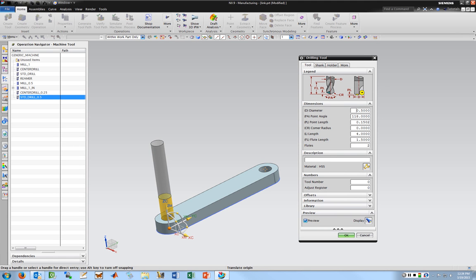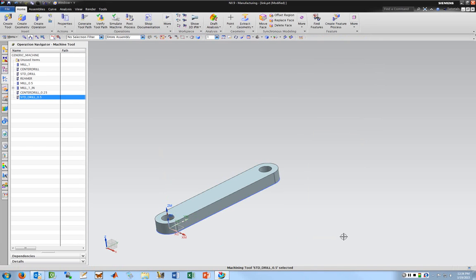At least I haven't had experience trying to do that before. But what I want to do is change the diameter to something under a 1/2 inch. So let's leave 10 to 15 thousandths. I'd have to look at a drill chart and see what the next smallest size is, but I'm just going to call it 485. There's probably something somewhere around that. Again, I'd have to get a drill chart to figure out the exact size, but that's 15 thousandths under, so it'll work. It'll make sense while I'm doing that in a second, but at least that covers how you edit tools if you get stuck with something you need to change.